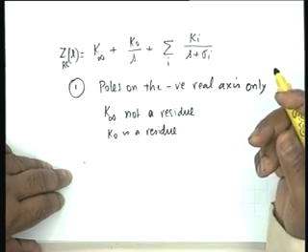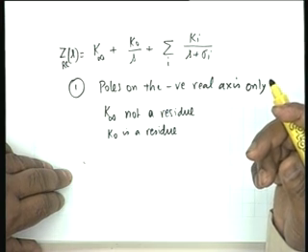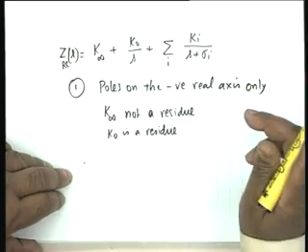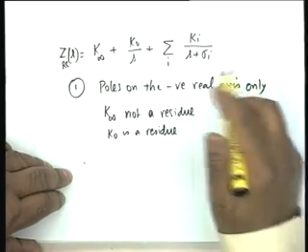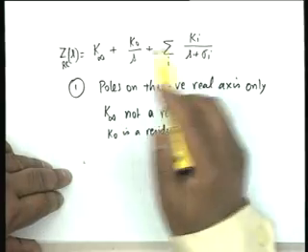At infinity an RC impedance, alright, let me repeat, at the origin an RC impedance can have either a pole, if K0 is not equal to 0, or a constant value. What is the constant value?